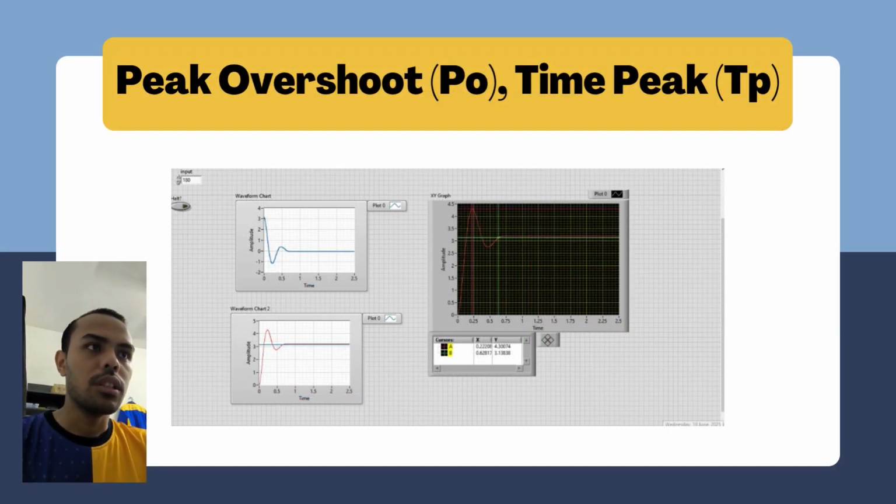Using the standard percent overshoot formula, our system reached the target with about 37.27% overshoot in only 0.228 second, as I mentioned before. This number suggests that the system is fast, but the overshoot also hints at slightly underdamped behavior, which is expected when prioritizing quick response.